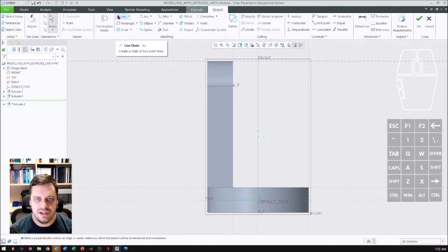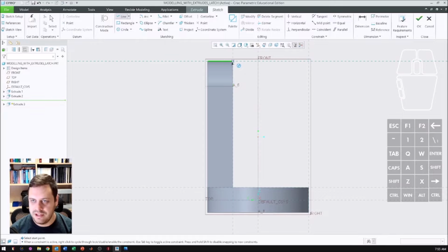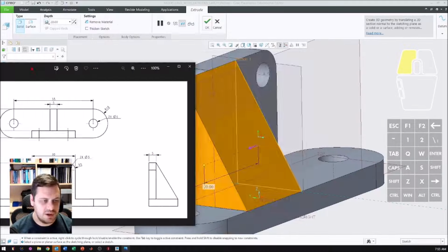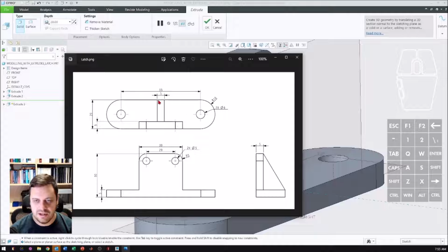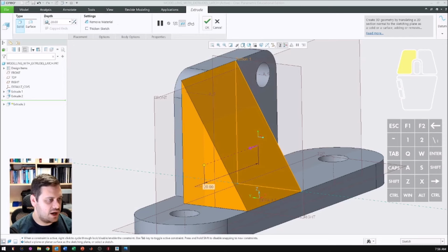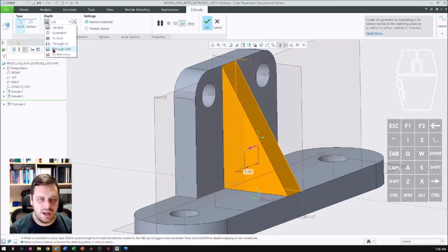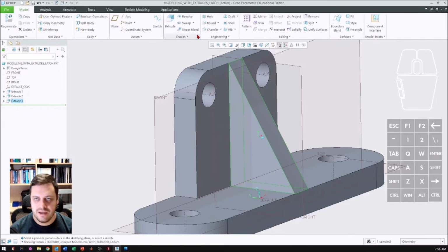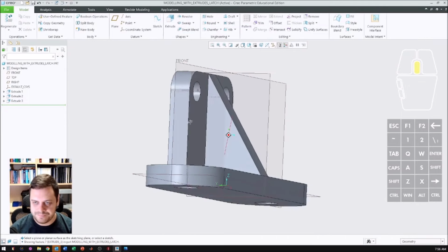Now what I'm going to do is select my line tool, and all it is simply closing the dots. So there to there to there and then to there. And then center click out, and then we can go OK. You can see that we're ready to go now. So if we bring this one across, we've got 5 millimeters where it's assumed to again be in the center of this particular object. So we're going to drag that one across, make that 5 millimeters, and then automatically change that to symmetric, and then click through and go OK, and then we're good to go.